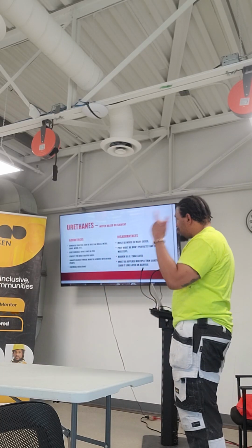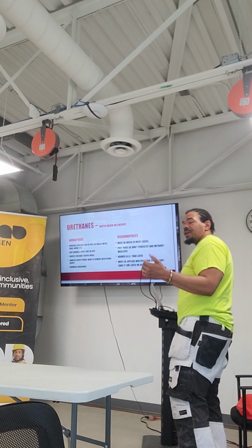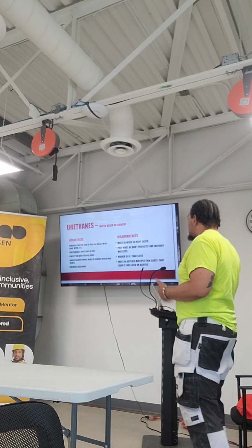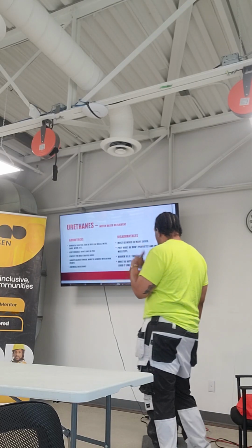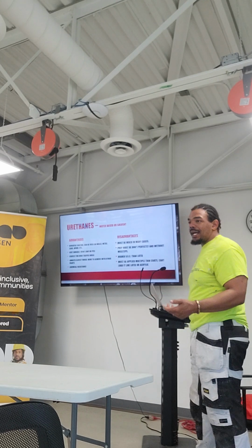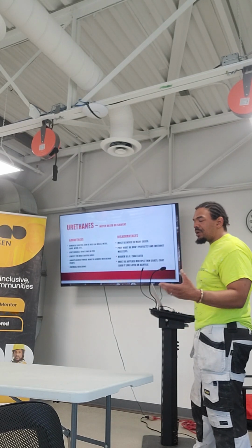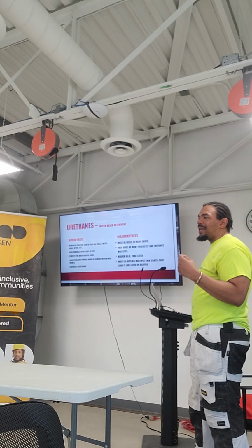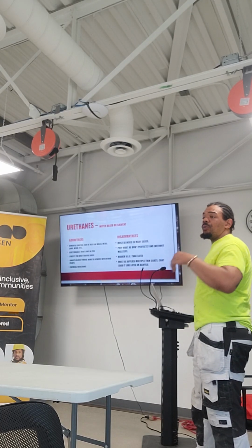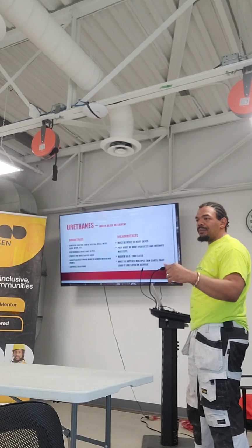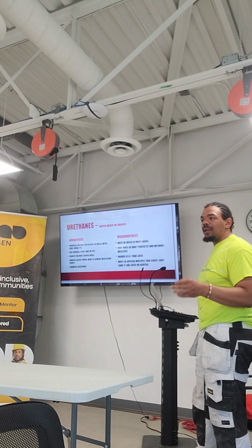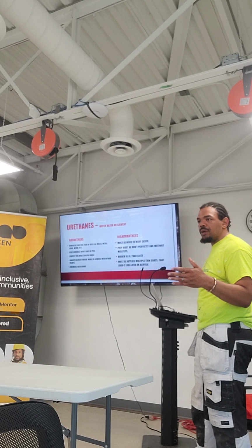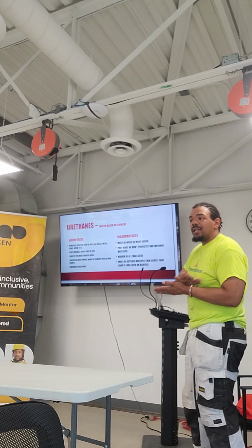Okay. So now you know how to do a scratch test, so if you want to make sure that your paint binds, you know how to do it. The disadvantages to urethanes: they have to be mixed, like I said, and catalyzed. Sometimes you have to let an induction period happen before you can use them. The prep has to be done perfectly. You cannot skip steps. Before, we said sometimes people won't sand in between coats. You have to make a mechanical bond, a mechanical key, for this material, and sometimes a chemical key as well.